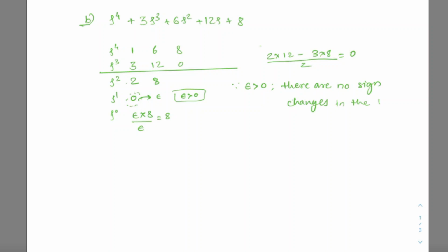If you quickly look at the poles, s is equal to plus or minus 2j. So these are complex poles on the imaginary axis. Here we are expected to try out different controllers P, I, D, PI and PD and check which of these stabilizes this particular system.